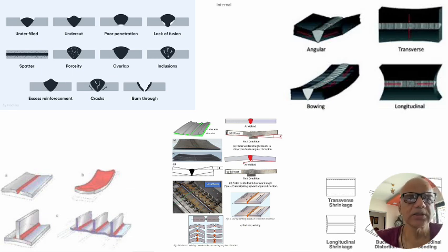Smooth transition is not a stress riser and it is good. Code recommends a 1:3 taper for any smooth transition in dissimilar thicknesses, or wherever you have transitions in the nozzle or in other areas in the pipelines or in the structural members.